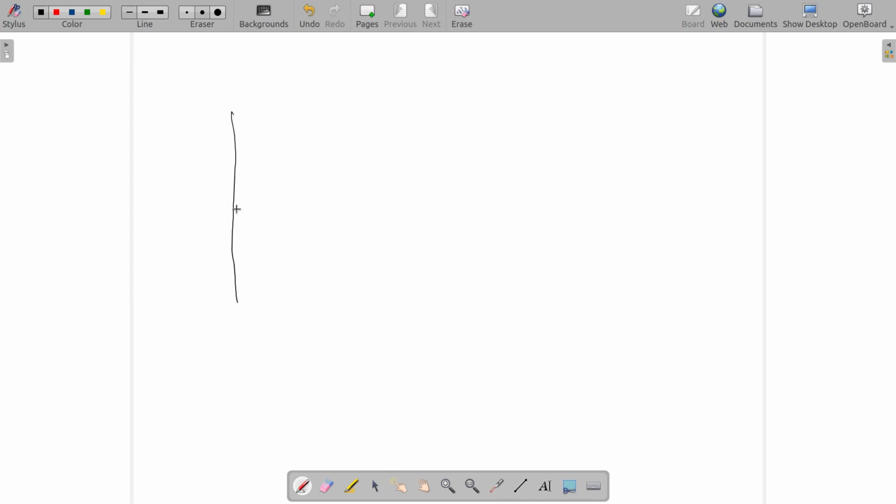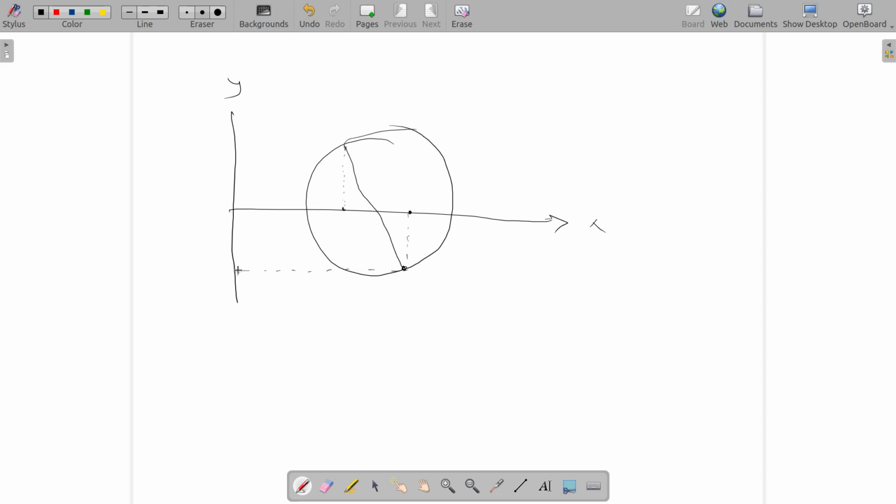Let's say this is our Mohr circle, and on the x-axis you have normal stresses, and there is always a diagonal which represents a plane which has a certain value of sigma x, and on the plane perpendicular to it you will also have sigma y acting on it, and the corresponding shear stress value will be here.